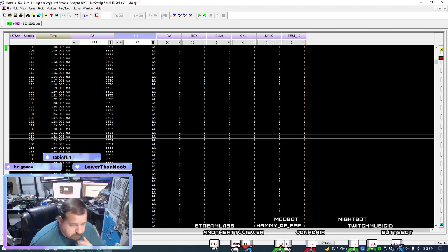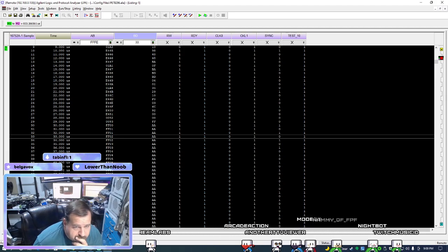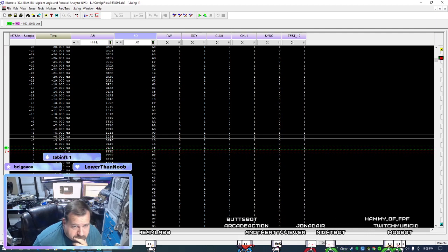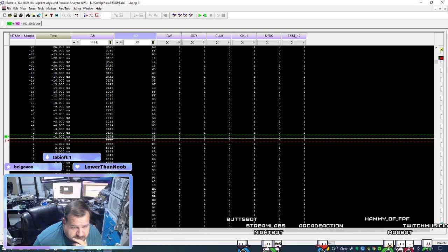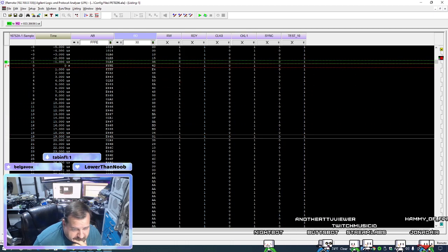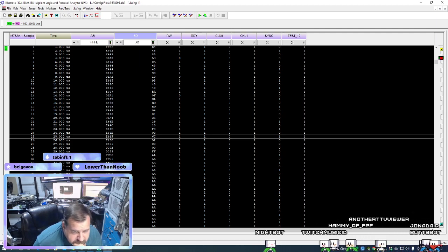Here's what's interesting. So yeah, this isn't right. This definitely is not right. So there's a reset vector. Loads the reset vector in. It's going through here. And then it jumps to, looks like FF00.